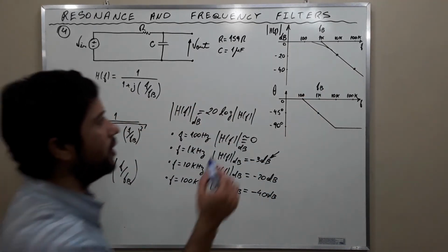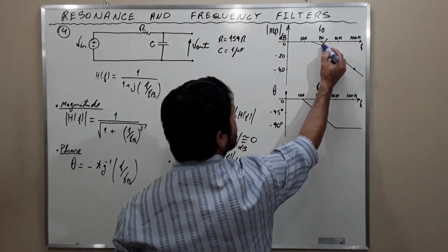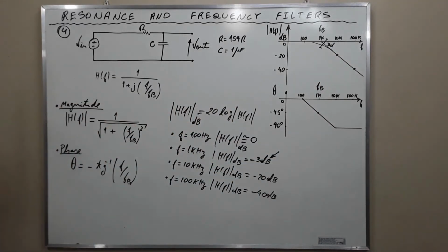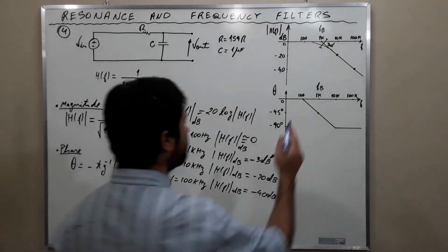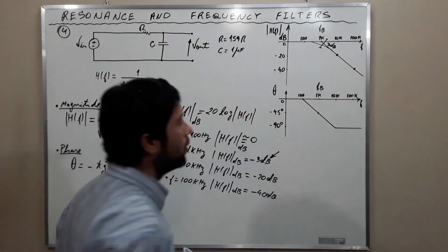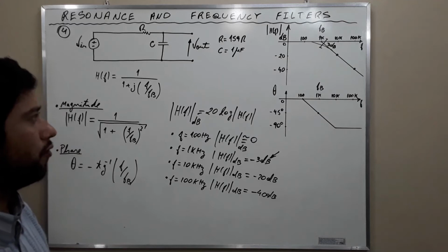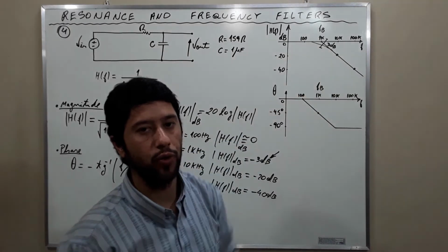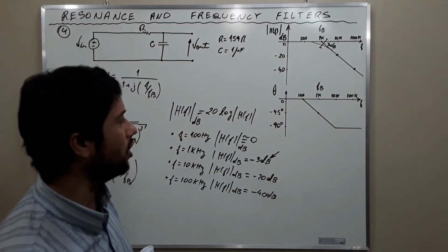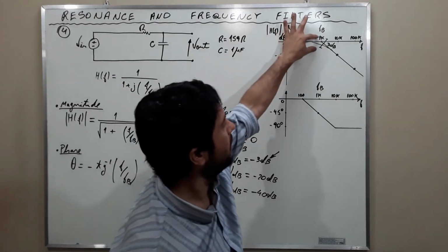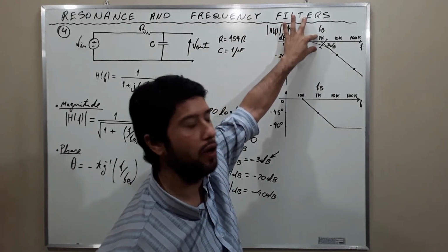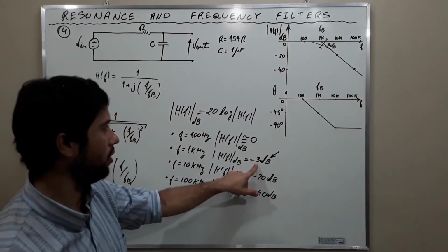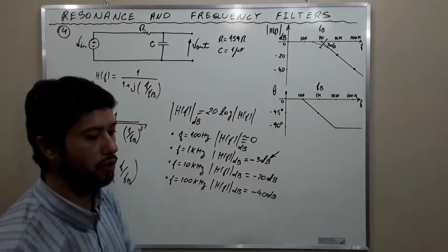And there is a deviation or an error of 3 decibels from the actual graph to this straight line approximation here that we frequently work with. Okay? So there is this deviation, or this error of 3 decibels at the cutoff frequency, which in this case is 1 kilohertz.